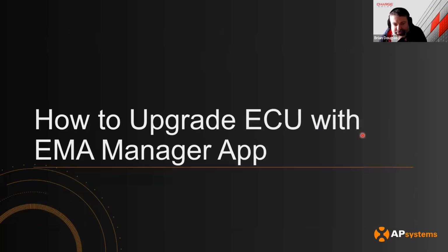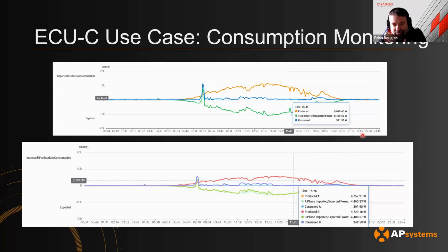Okay, there's a few questions on the CT side of things here. Given the ECU can measure grid CT and production CT, can the APsystems system derate the production to ensure the bus bars in a residential panel are not overrated? Like oversizing, but then reducing the production curve, essentially. Yeah, that's a really good question. We call this feature export control, because you're controlling the export of power going to the grid, and that is something you can do if you have CTs installed.